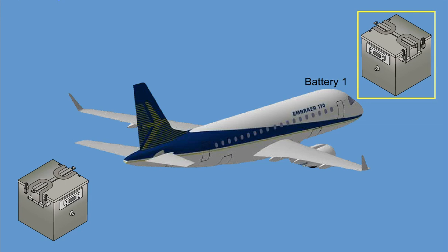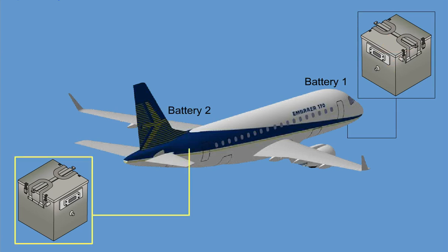Battery 1 is located in the forward E-bay directly below the SPDA-1 unit. It provides stored energy to selected equipment during normal operations and during flight in the absence of all other airplane electrical power. Battery 2 is located in the aft E-bay. It also provides the power used for an APU start through the APU start bus during ground or flight operations, when the electrical system is automatically isolated from Battery 2.